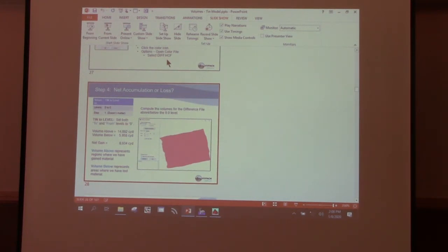So we developed a way where you can take the XYZs in as a matrix, and then load the matrix in as a template, and then you can cut to that irregular surface. Originally, we tried to load it into CHN files. And if you make a tin of something, you can actually go File, Save Tin as a CHN. So you can generate a tin of a small area.